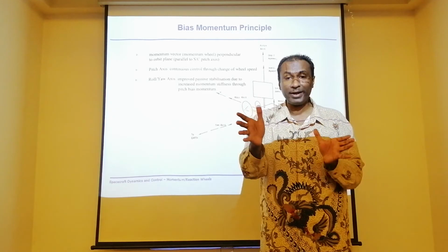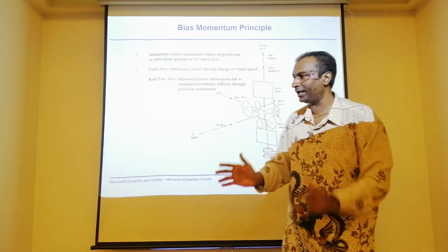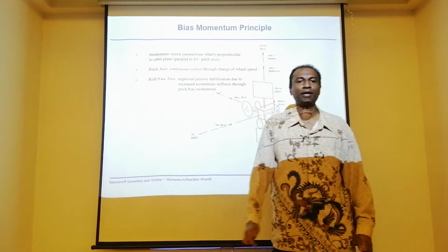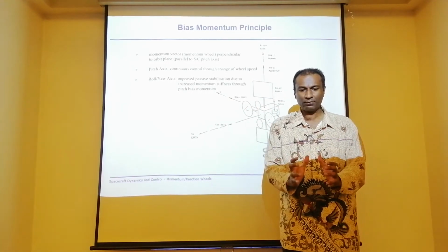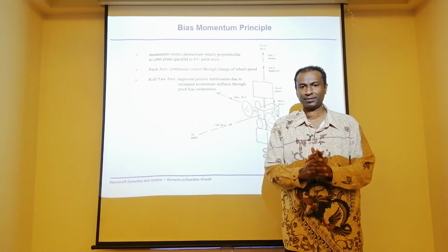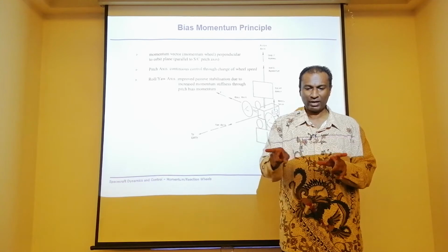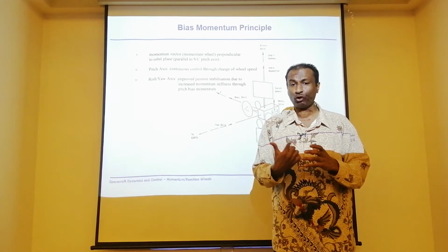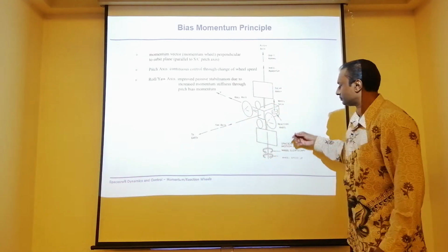The roll and the yaw axes are basically going to be quite stiff. So therefore it increases the stiffness of roll and yaw axes by putting the momentum wheel in the pitch axis. But that is all. It gives you a stiffness to roll and yaw. But don't forget, for the pitch axis, it can produce active torque when you start speeding up the wheel. Okay, go on.